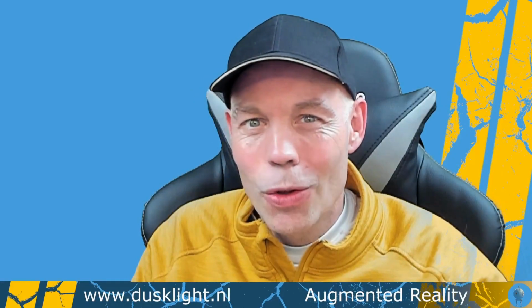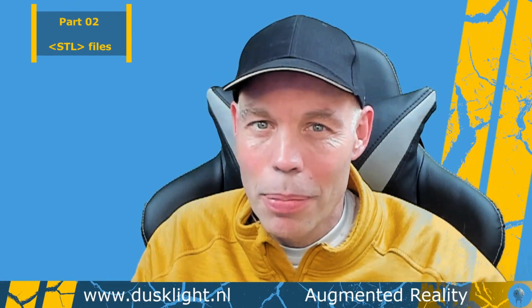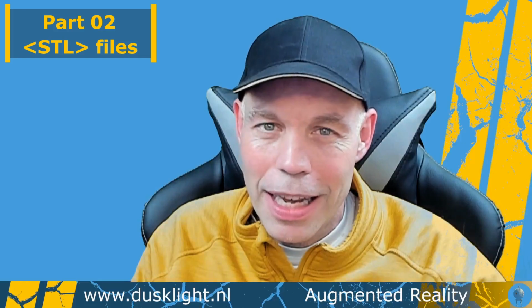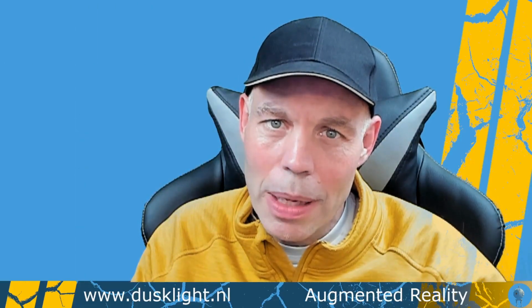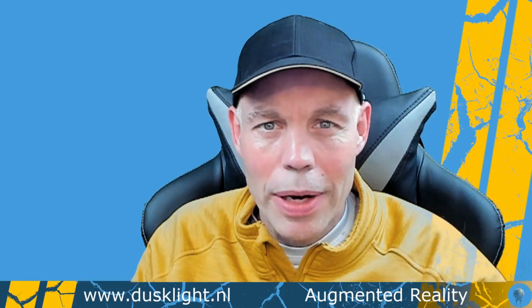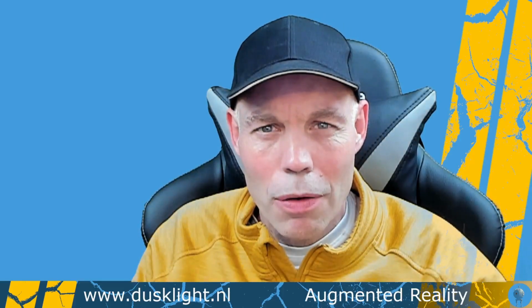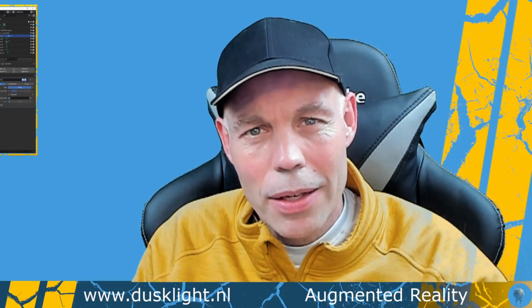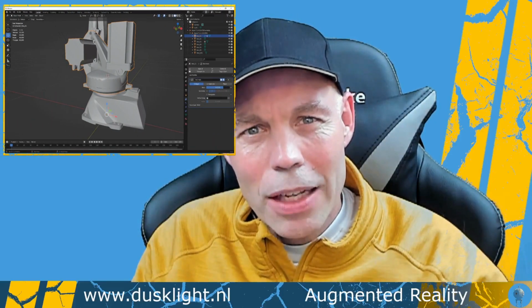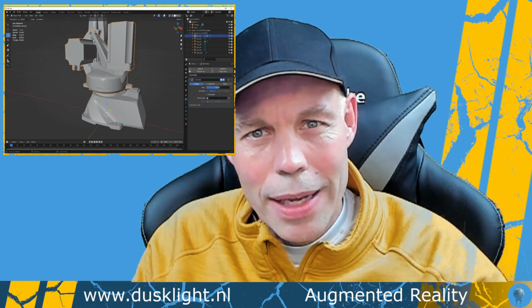And welcome again to a new tutorial, the second part in optimization of an engineering model. In part 1 we looked at a step file, importing it into Blender and optimizing it through the process of removing unnecessary geometry or applying a decimate modifier. And that's all done to reduce the triangle count.